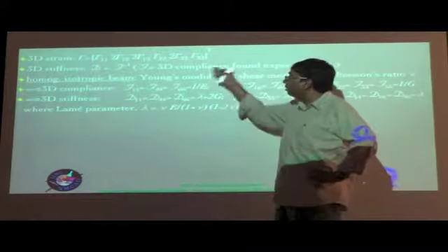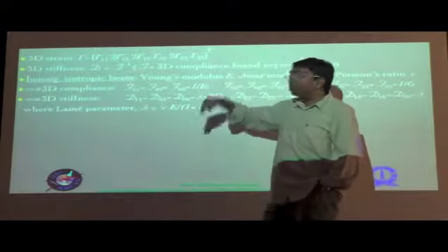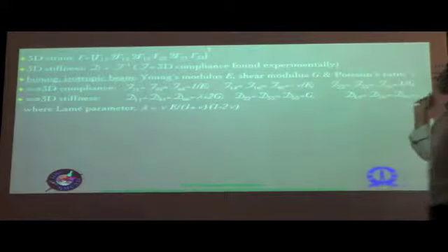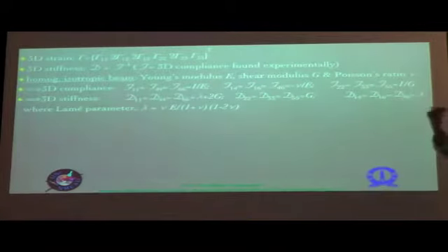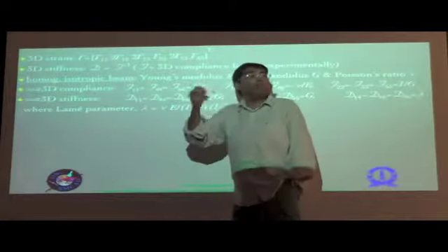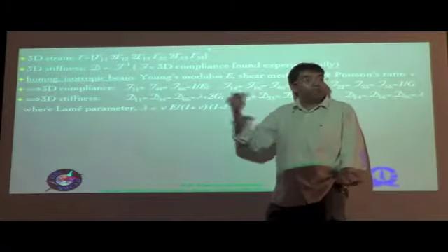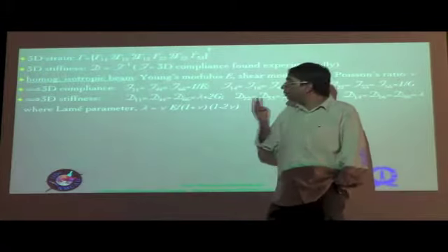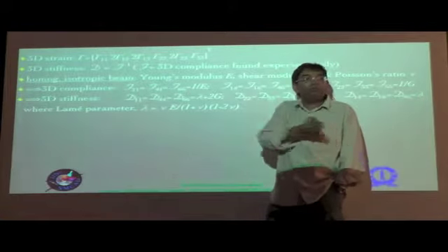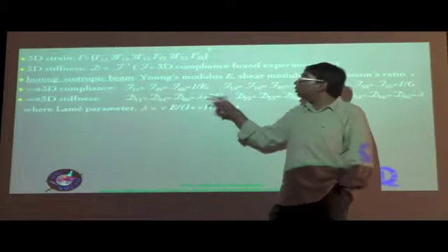That's known because we're talking about an isotropic beam. Many of the couplings are absent, but amongst the terms which are present, all are of the same order of magnitude is an assumption that we typically use. It seems to be reasonably good if nu is of the order of 0.2, 0.3, which is what is observed for most structural materials that we use. But you should remember that if you're talking about all kinds of materials, you have to look at this entire range, minus 1 to plus half, and in such situations you can have issues.